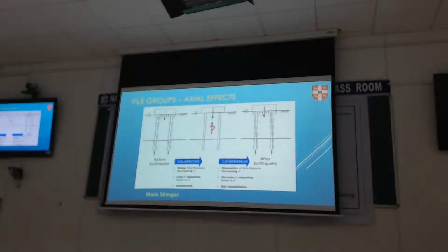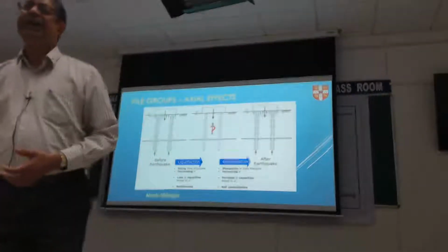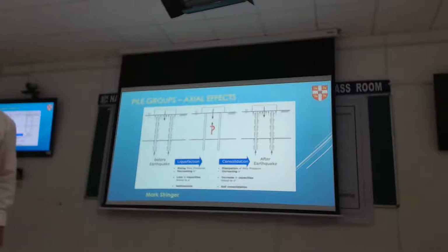We don't know. What we know, of course, is that post-earthquake, this situation must be the same as that. So you'll have consolidation, the soil will come back, it gains its strength, and your effective stress goes up as the pore pressures dissipate, so you have increasing capacity. So we know that in the long term we will have the same or a similar setup as this. Not the same because the soil has reorganized itself, but from an equilibrium point of view, it should be true.